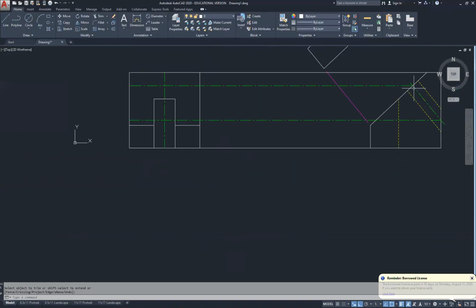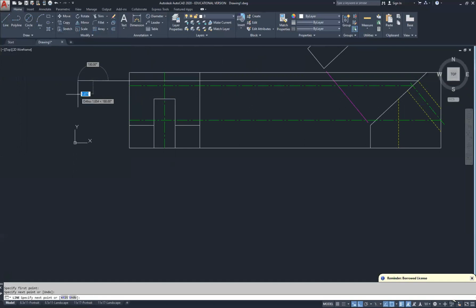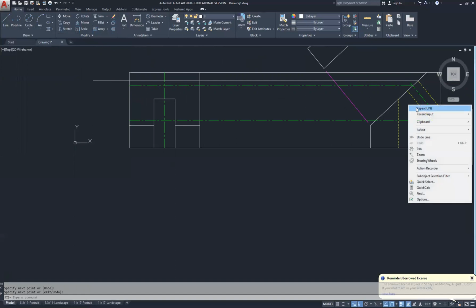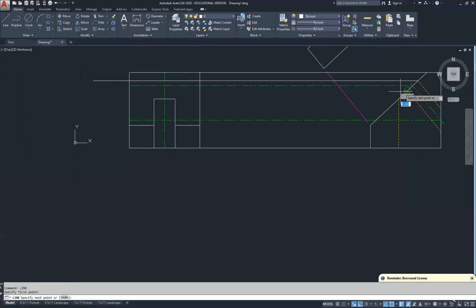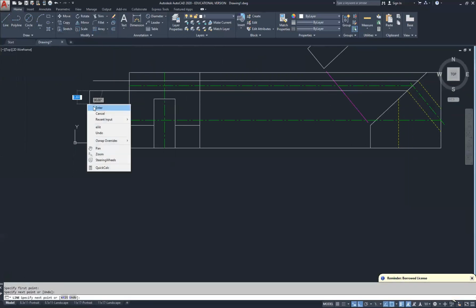I'm not looking at that perfect circle that I had here earlier. I'm now looking at the circle as if it's laying on that face. So what I'm going to do is project these hidden lines from here straight across. I'm going to go past the object, just so I know that it's not referencing anything particular besides the hole. I'm going to go straight across here.